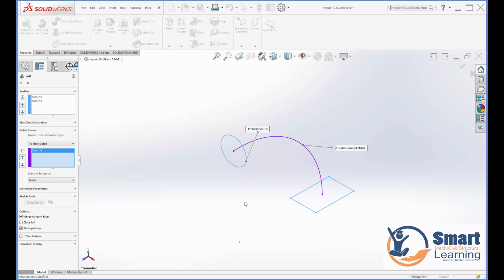What happened here is, if you go to this particular sketch, somewhere the starting and ending point references are not correct, and based on that you are not able to form this. Then how to fix that? That is one point here. So let me add this under the sketch, and this is your path.